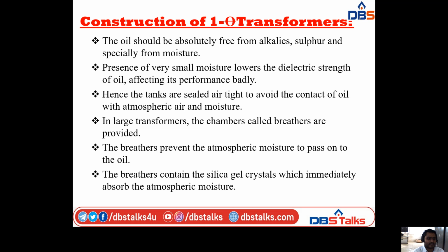In large transformers, chambers called breathers are provided. The breathers prevent atmospheric moisture from passing onto the oil. The breathers contain silica gel crystals which immediately absorb the atmospheric moisture.